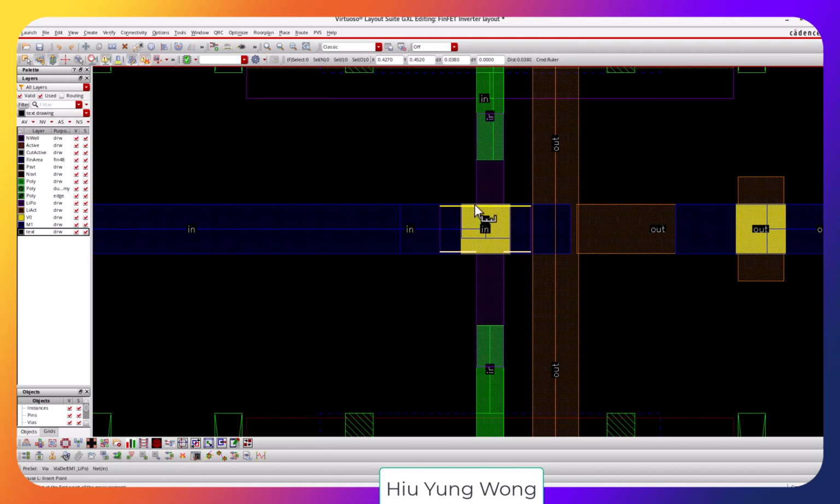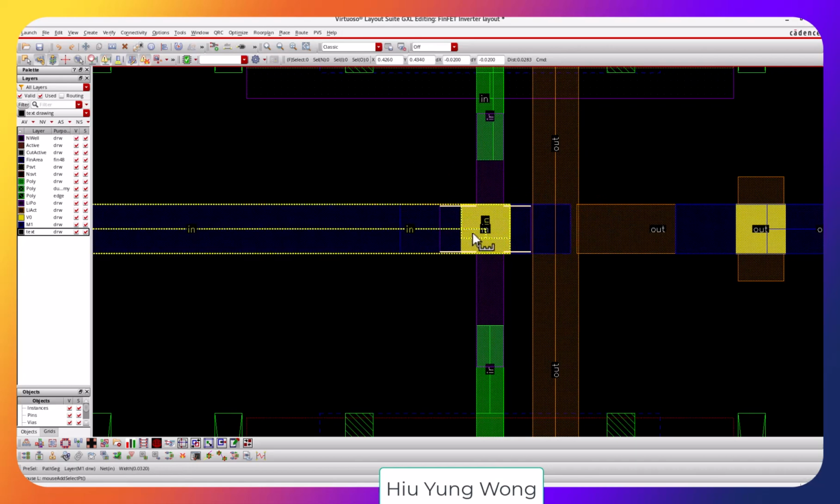Shift K to erase the ruler. And then again, I'm going to use K, and then click on the edge and try to see where it is 0.04, right? So, and then I click on it, 0.04. Same for this side. K. Click on it. 0.04, right? But then it's going to extend all the way to there. So maybe that is not a good idea to just add something, right? So what I'm going to do is just Shift K to erase the ruler.